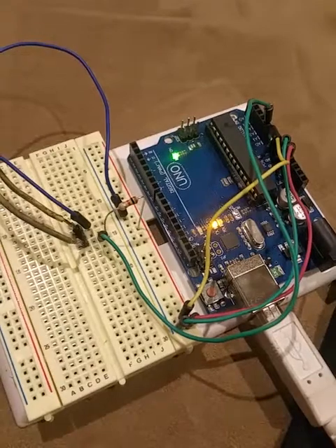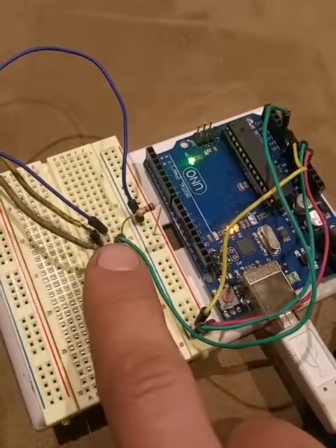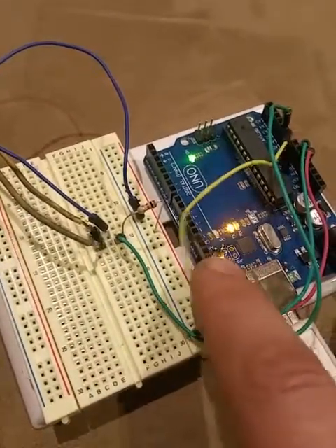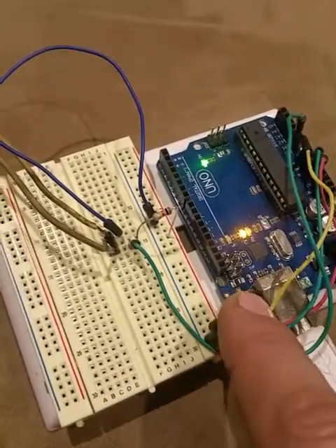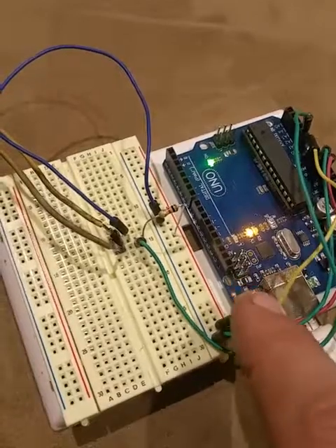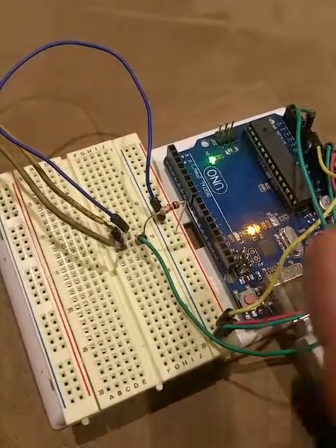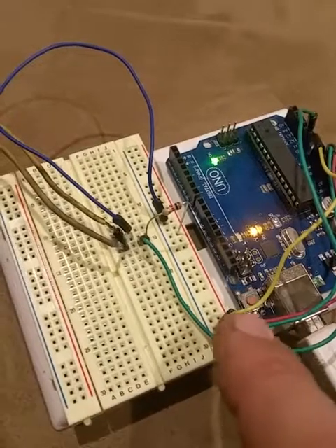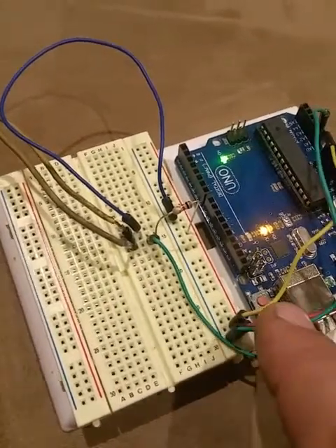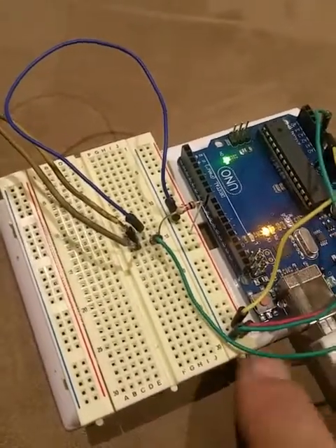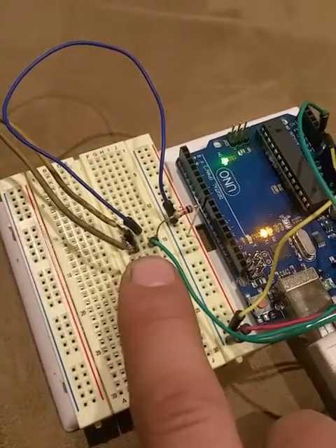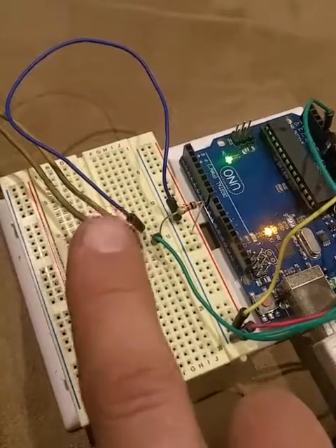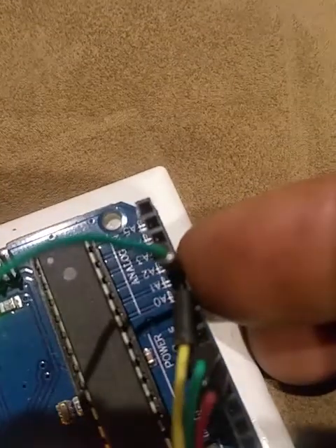So what it's going to do is read the 5 volts on this yellow wire, just so I know exactly what voltage it is, close to the 5 volts it's trying to aim at on my 5 volt line. If there are minor fluctuations in the voltage regulator, it might be 5.01 or 4.99. This just ensures accuracy of the reading. This wire right here is going to read the voltage between my voltage divider, and then I can calculate the resistance of the temp sensor with it. And that voltage is going to be read by pin A1 over here.